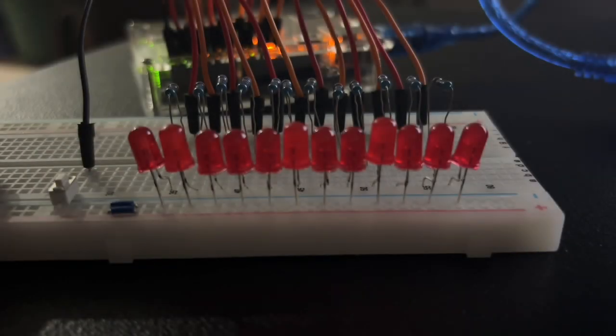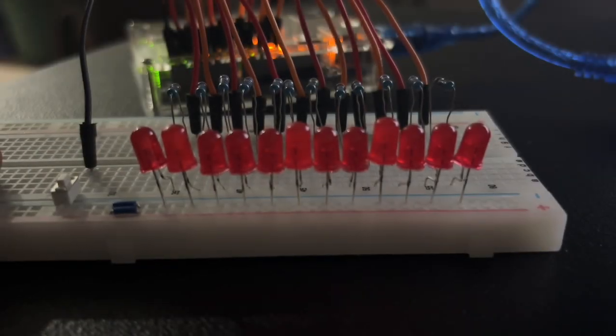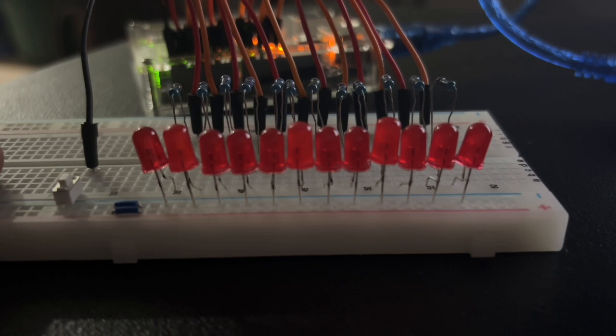For this activity, I will explain how my Arduino program and circuit perform the required functions stated. When the Arduino program starts, all 12 LEDs are initially turned off. This is done in the setup function, where each LED pin is configured as an output and explicitly set to low. This ensures that no LED lights up unintentionally when power is applied or when the program is reset.